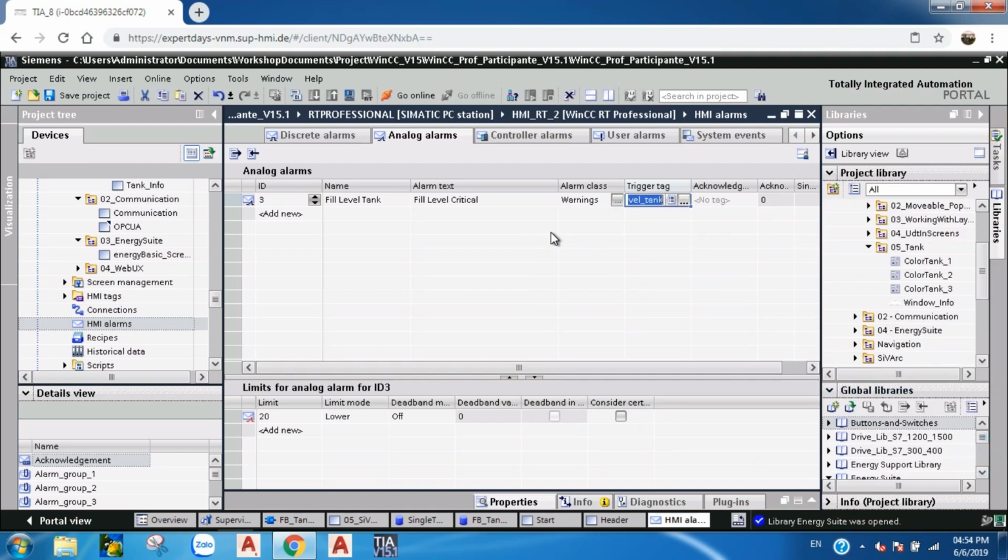It also has the alarm text "filling level too low 4", so the static string, and it adds single tank 1, single tank 2, single tank 3, so the symbolic name of my FB. Same for name: single tank 1, the symbolic name of the FB, underline my static string, which I set in the script, alarm underline tank. That's it.